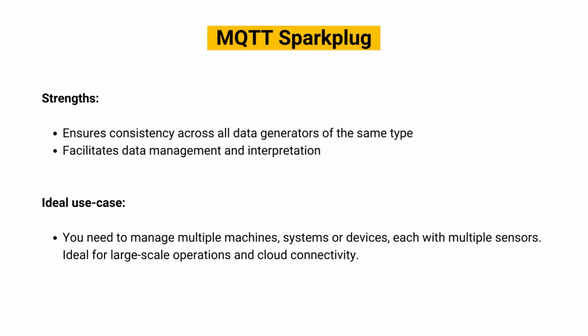MQTT Sparkplug shines in situations where you need to manage multiple machines, systems, or devices, each with multiple sensors. Sparkplug's use of templates for complex data types ensures consistency across all data generators of the same type, facilitating data management and interpretation. Moreover, Sparkplug's emphasis on data type definitions and efficient bandwidth utilization makes it ideal for large-scale operations and cloud connectivity where communication efficiency is paramount.